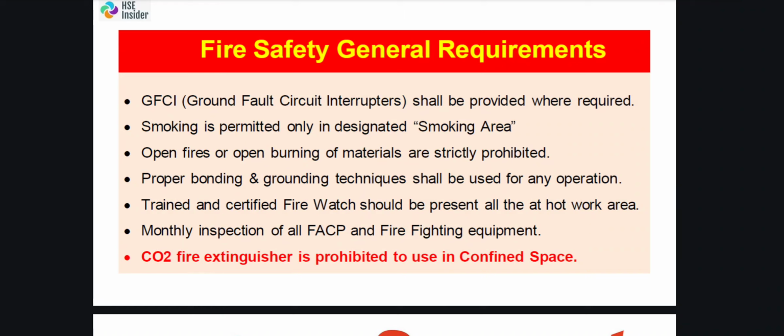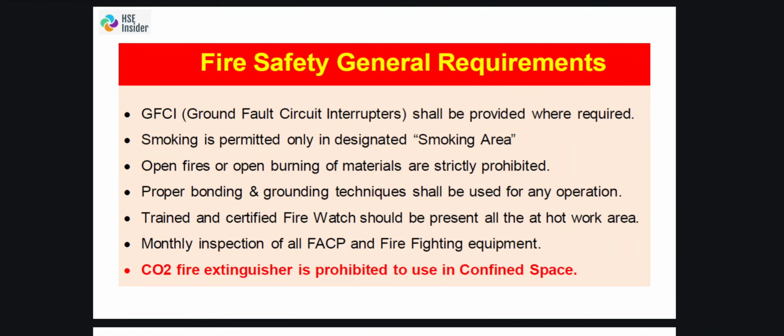Smoking is permitted only in a designated smoking area, so please form a designated area for smoking. Open fires or open burning of material are strictly prohibited, so don't allow open fires or open burning of any waste materials or vegetation in the workplace. Proper bonding and grounding techniques shall be used for any operation. It is very crucial to control static.